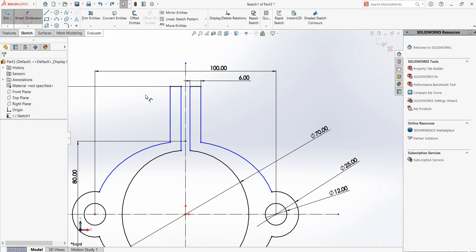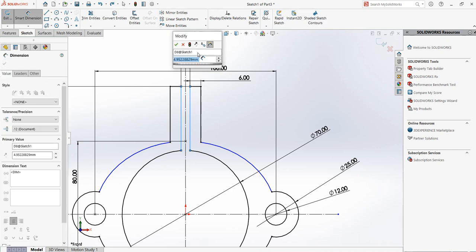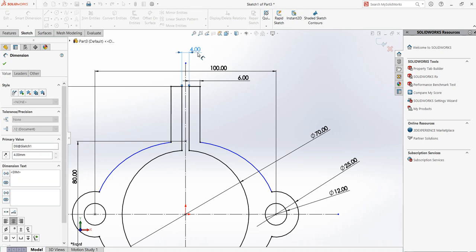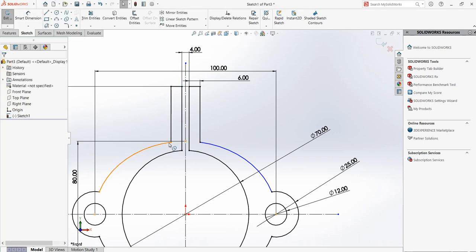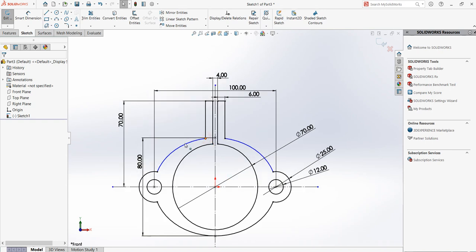Now I will use this dimension for, yeah, now it's okay. What I did was, before I did the horizontal constraint, I removed the horizontal constraint. Sometimes if you constrain, it will not allow the geometry to position itself. So you need to see what is actually stopping you from getting it fully constrained. So now the gap is 100. Now this one is still unconstrained.